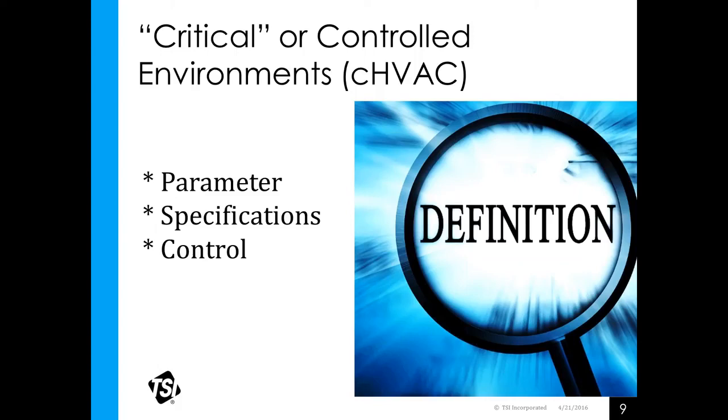Temperature is always a measured parameter. If you're doing balancing work, any of the TAB guys out there, if you're careful, you can balance a room using just temperature and not any other measurement. But it's an essential part right alongside relative humidity. That's the other side of comfortable, I like to call it. So they both go together.